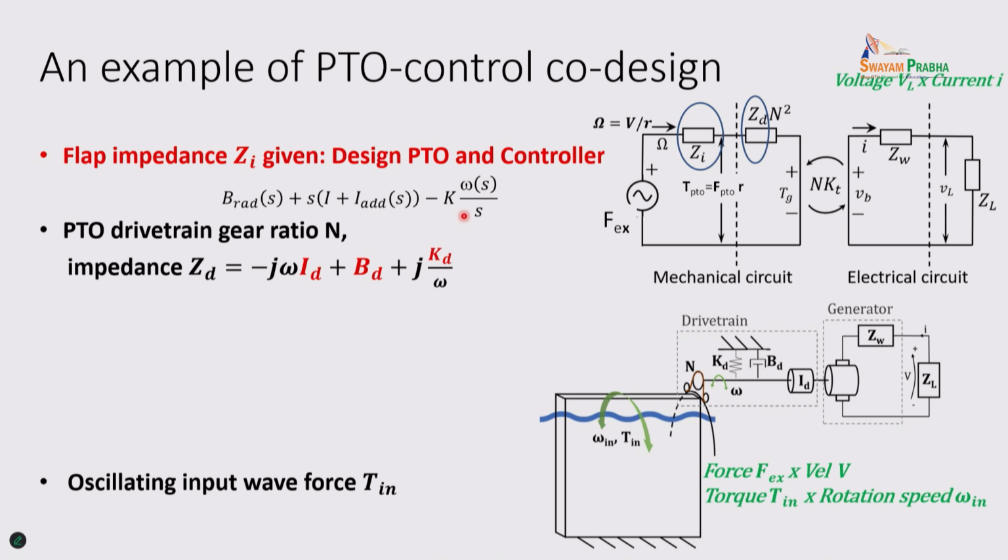And the second part is the PTO's efficiency, impedance. And the PTO is a powertrain system, right? You may have the rotation inertia, right? You will have mechanical damping in the ball screw system. You can have PTO stiffness, right? That is the impedance of the PTO side. Again, you just imagine it that way.